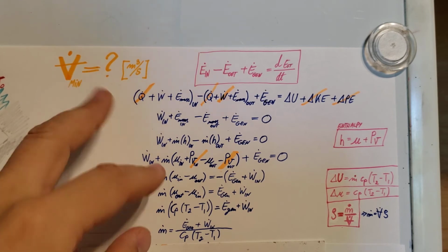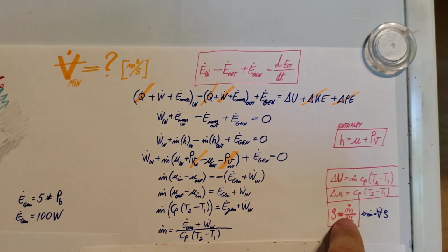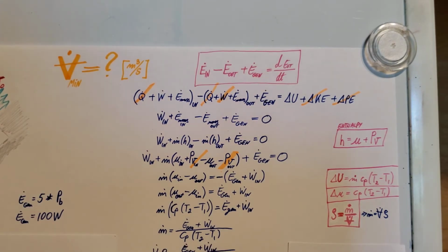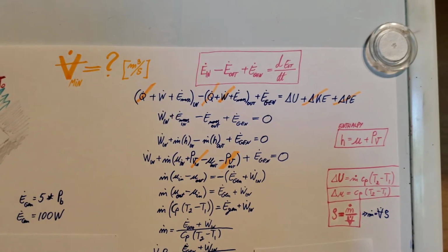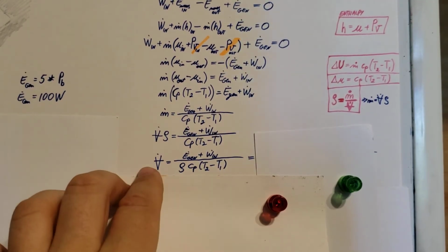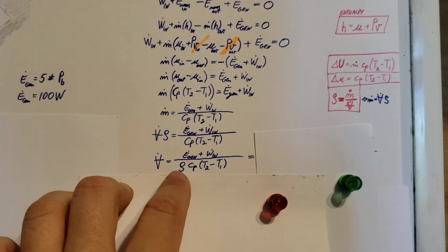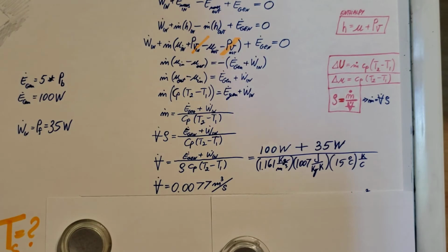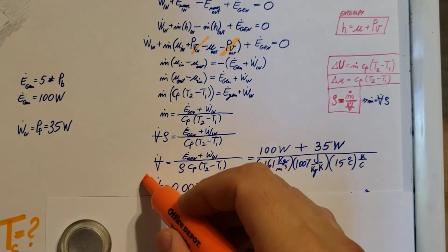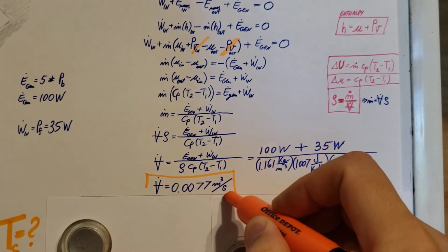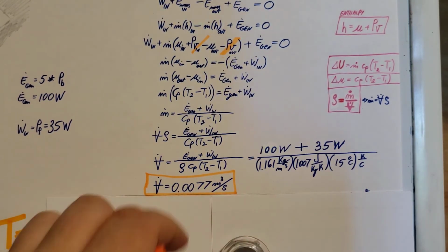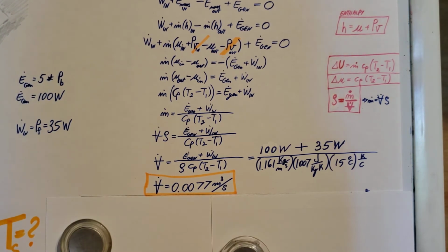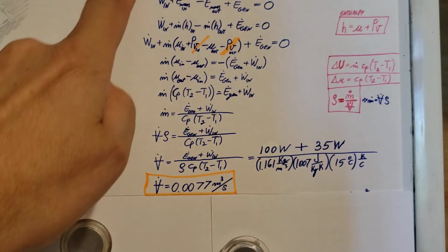They're asking for volume flow. So let's go ahead and use our very first formula that we thought of, this one. Now I'm going to solve for mass flow right here, volumetric flow times the density, plug it in right here. Now I have it solved for volumetric flow, everything we know here, so we can go ahead and plug in. There it is, and after a little bit of number crunching, we can find our volumetric, wow, I couldn't say it, flow rate right there, 0.0077 meter cube per second. That's what we needed.